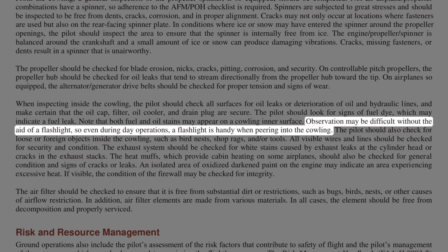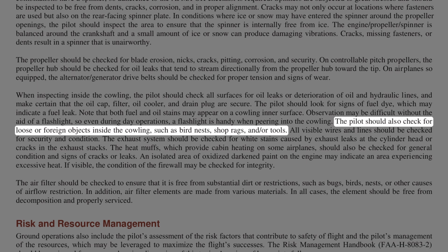Observation may be difficult without the aid of a flashlight, so even during day operations, a flashlight is handy when peering into the cowling. The pilot should also check for loose or foreign objects inside the cowling, such as bird nests, shop rags, and/or tools.